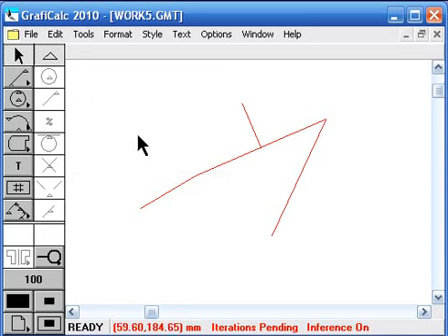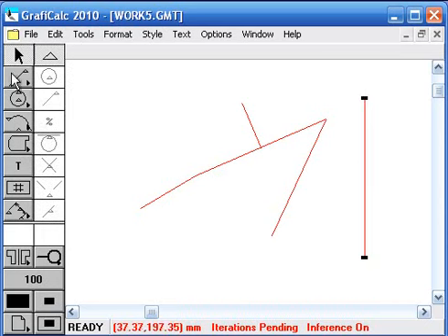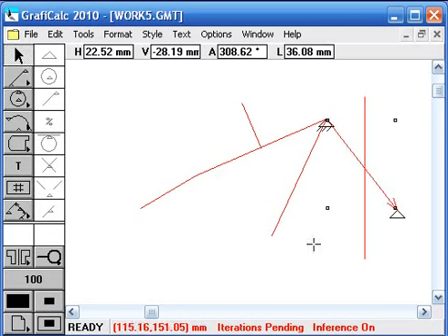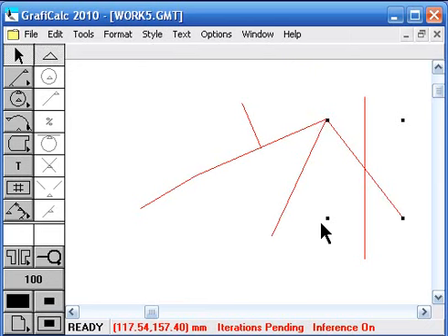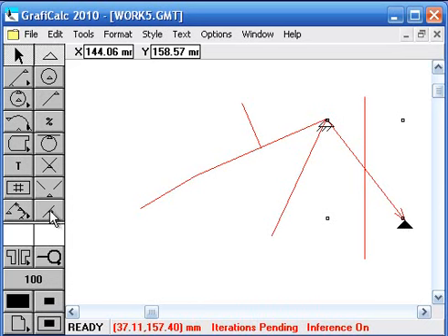You can also create a slider mechanism. For example, I want this to drive this link. So here it's a specific situation where the length constraint has to be given directly to the line using the value bar. The drop point will not work here because that will be over constraining the line, because I'm going to make that line slide. I'm going to make this point slide on this line here.